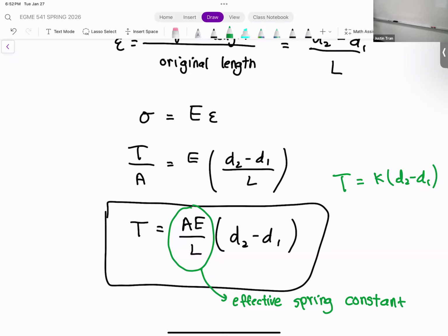Here we kind of jump a few steps. The force, technically, you can relate to a stress on the structure. And a stress is essentially a derivative, related by a stress-strain relationship. So we kind of jump to it. In a technical sense, a Neumann boundary condition sets the derivative equal to something. Most commonly you'll have a stress-free boundary condition, which is derivative equal to 0, but you can set that derivative equal to whatever.